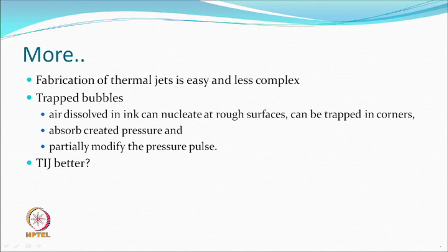So, thermal inkjet, although simple, may not be able to be used for pigment printing inks, which these days include the binder within the ink formulation, which obviously gets polymerized when you heat later, but it can happen during this process of generating pulses.